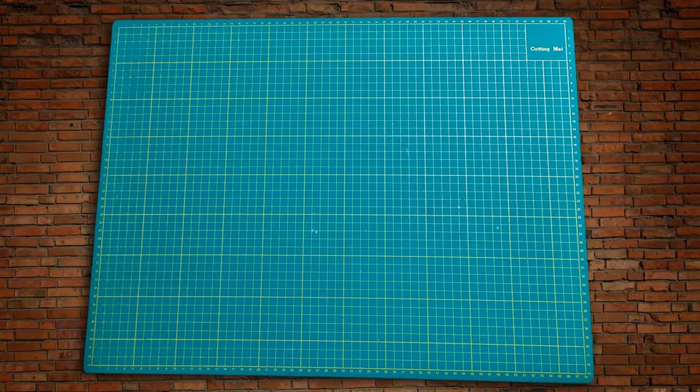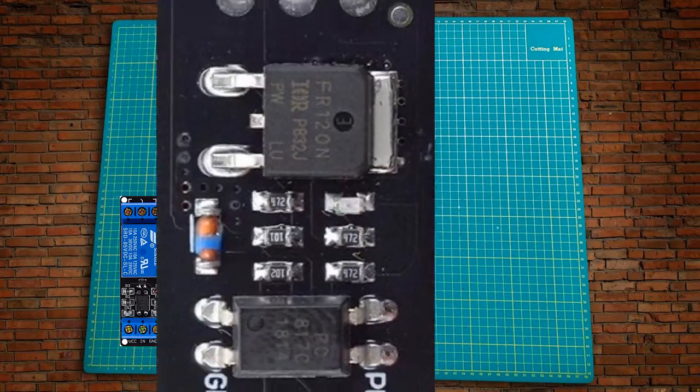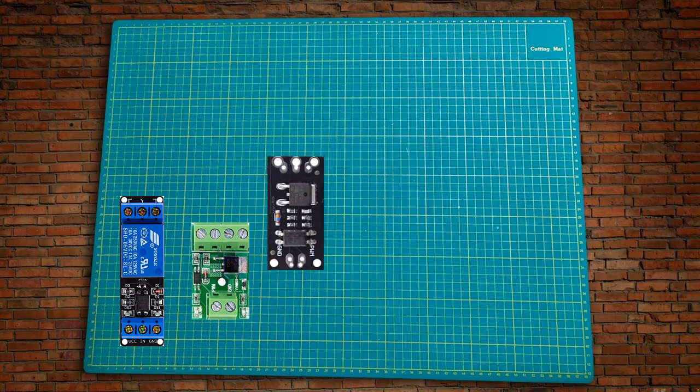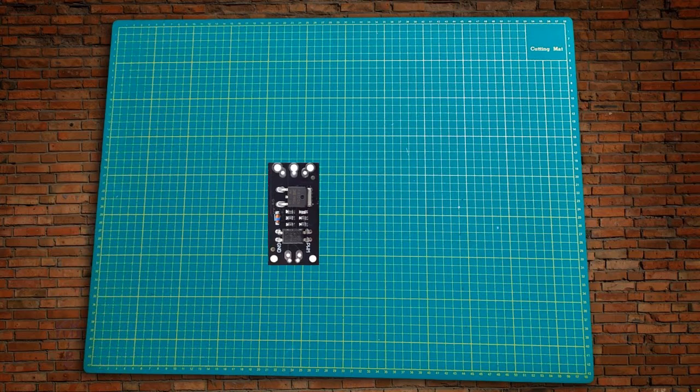As components for switching AC and DC loads, you can take mechanical relays with control from 5 volts with optical isolation. It is important to consider their life cycle, which is significantly inferior to solid-state relays SPDT using MOSFET transistors. Modules based on MOSFET switches with optical isolation are compatible with any controllers, for all types of AC or DC loads, including PWM signals. We did not begin here to focus your attention in detail on their types and structural features. This information is available in many articles on popular sites for electronic components with recommendations in their selection.